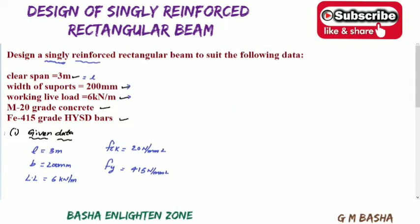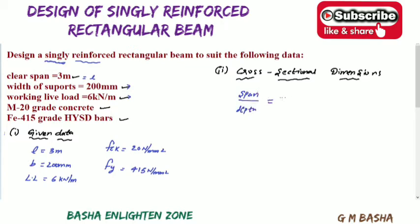Then our next step is to select the cross sectional dimensions. Cross sectional dimensions means in this we have to find everything like effective depth, overall depth, all the things. So here, for cross sectional dimensions, you can select based on the span to depth ratios, that is L by d.